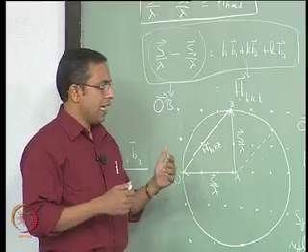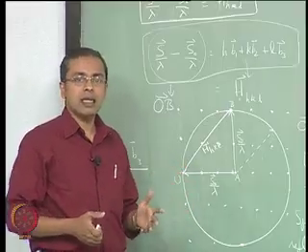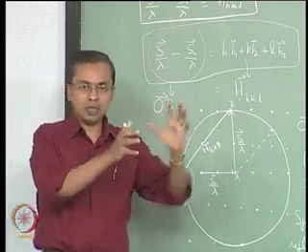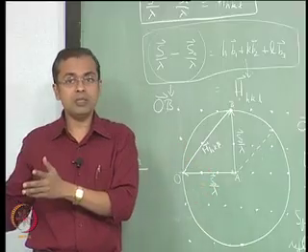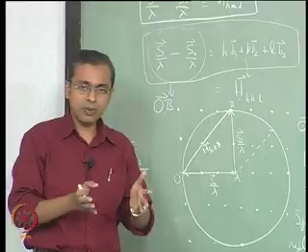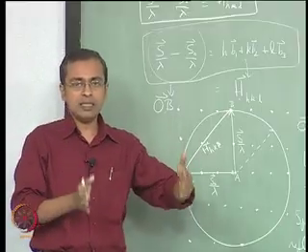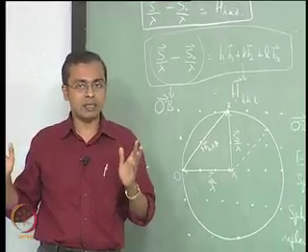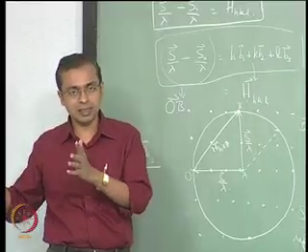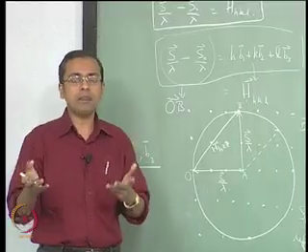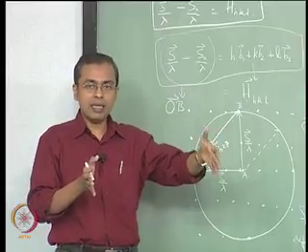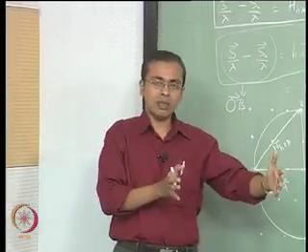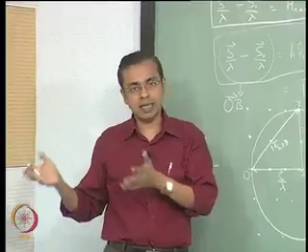That is one piece of information. We have also seen in this class that when you do this transformation from real space to reciprocal space, a structure that has a certain geometrical layout in real space may have a different geometrical layout in reciprocal space. In the case of simple cubic, it happens to have the same layout. In the case of FCC and BCC, it has a different layout in reciprocal space. The information is still the original material's information; it is only the representation in reciprocal space that has a certain layout. It so happens by chance that when you take a face centered cubic material, its representation in reciprocal space is that of a body centered cube, and if you take a body centered cubic material, its representation in reciprocal space is a face centered cube.